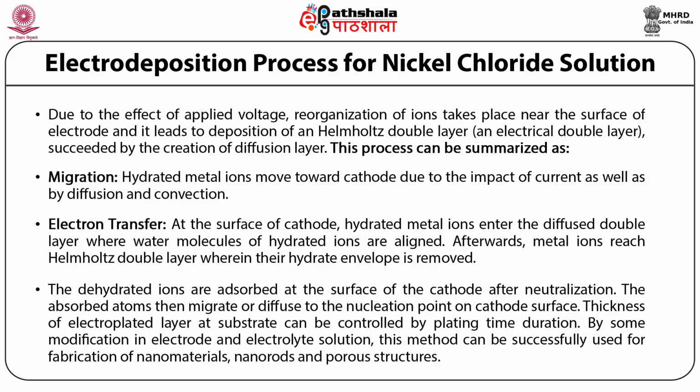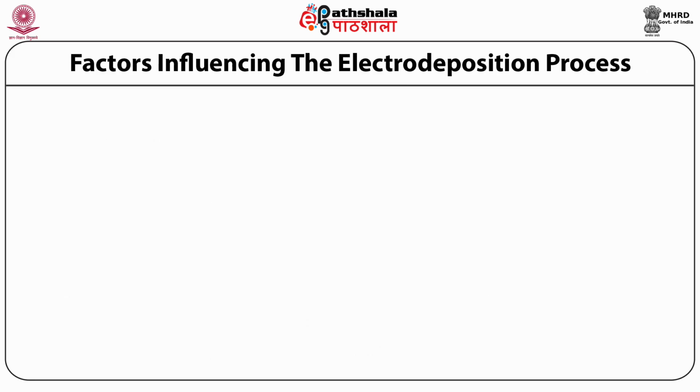Thickness of the electroplated layer at the substrate can be controlled by plating time duration. By some modification in the electrode and the electrolyte solution, this method can be successfully used for fabrication of nanomaterials, nanorods, and porous structures.